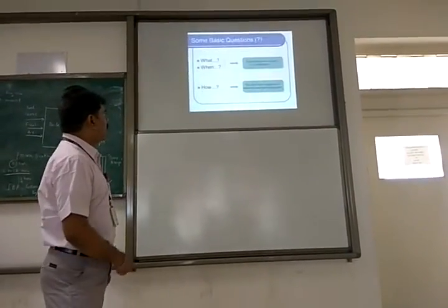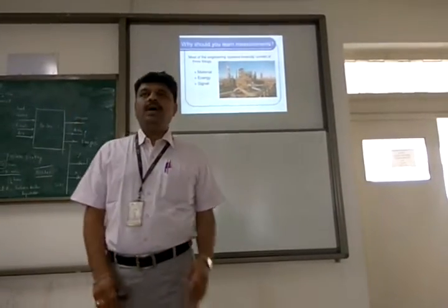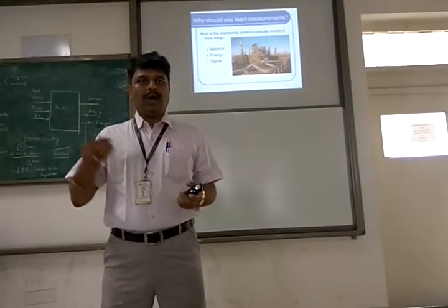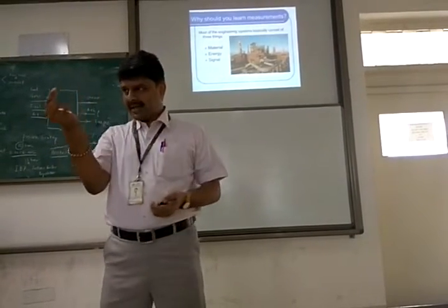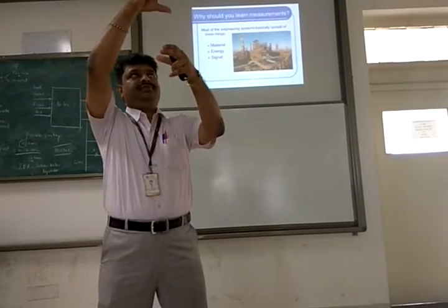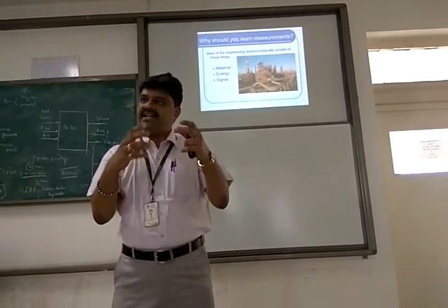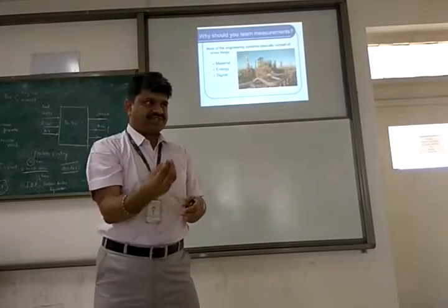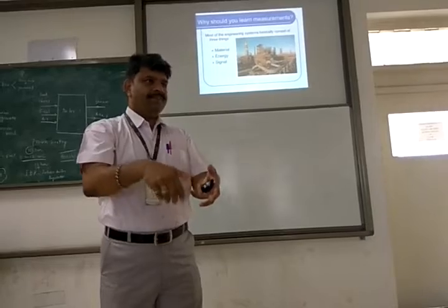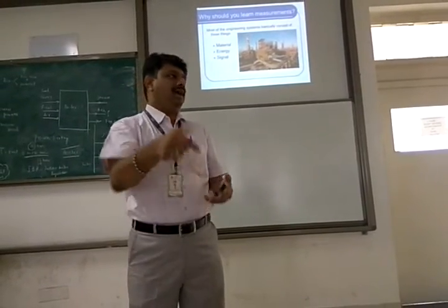Okay. Now, take an injection molding machine. You know what is meant by an injection molding machine? You have small plastic beads, like plastic tablets. From the hopper, it goes to a heater. In the heater, it gets heated up and comes out as a paste through a die, a small hole. That is sent to a die under pressure, and it forms the shape of the die inside.